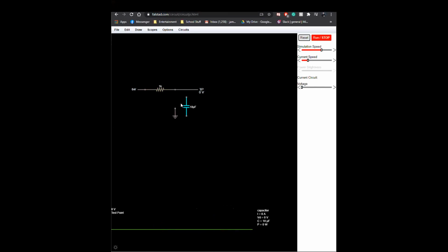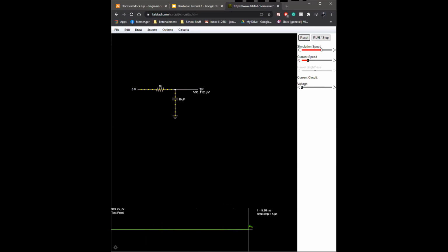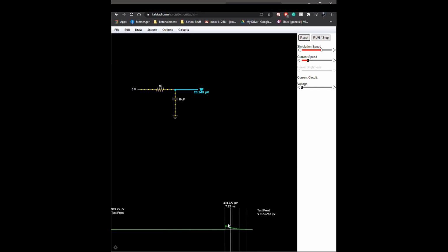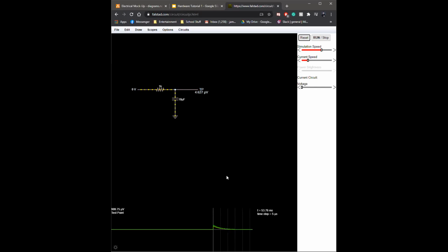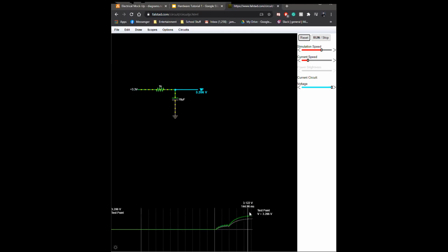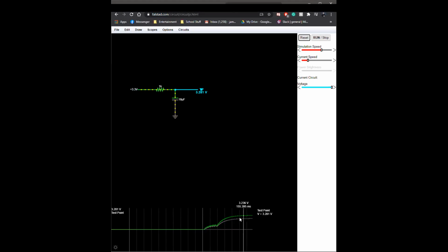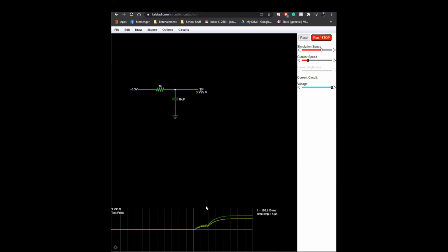But I can quickly put this capacitor back in. And if I start the simulation, the button's off at the moment, there is a bit of inrush. You'll probably learn about inrush later, not too important at the moment. But as you can see, if I do a really quick on, off, on, off, on, off, and then on, so I just flick the slider a whole ton, you see it doesn't actually go to the 3.3 volts. If I pause it here, you see these bounces? That was the button doing the bouncing.